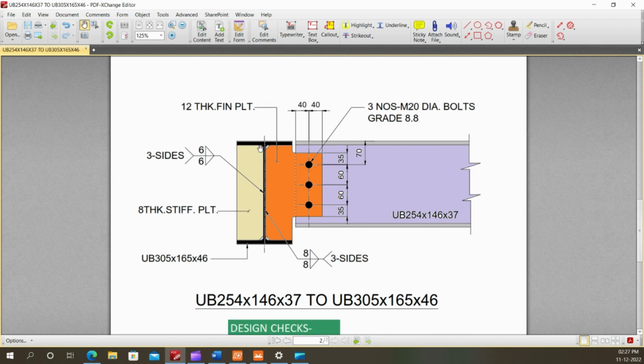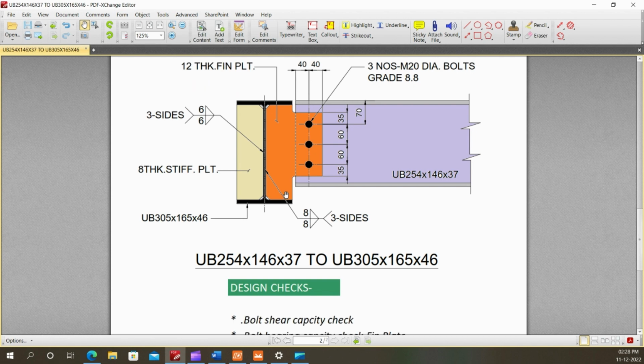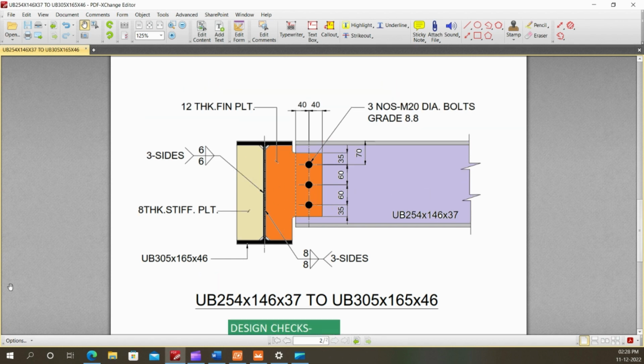The examination of the bolt group or the weld is a key aspect of connection design in any type of connection. There are two methods. One is elastic, which is also covered in the AISC manual, and another method is inelastic analysis, also known as the instantaneous center method. The elastic approach divides the loads into two components: direct shear and a moment. The direct shear is distributed evenly across all the bolts. The moment is transferred to each bolt based on its proximity to the bolt group CG.